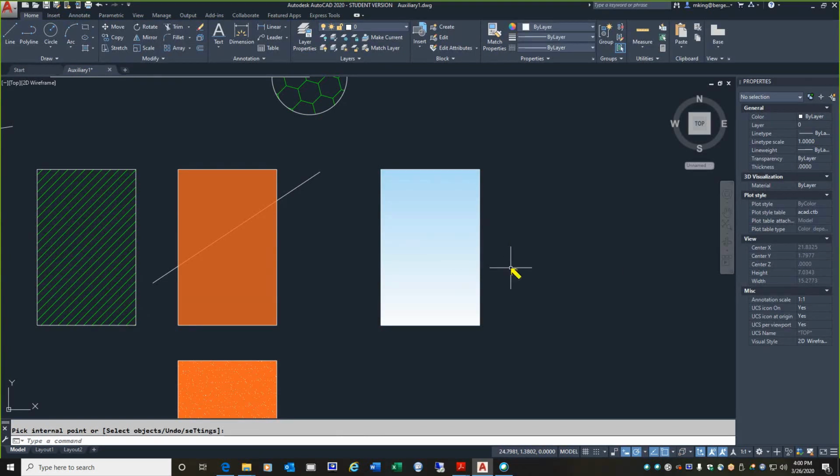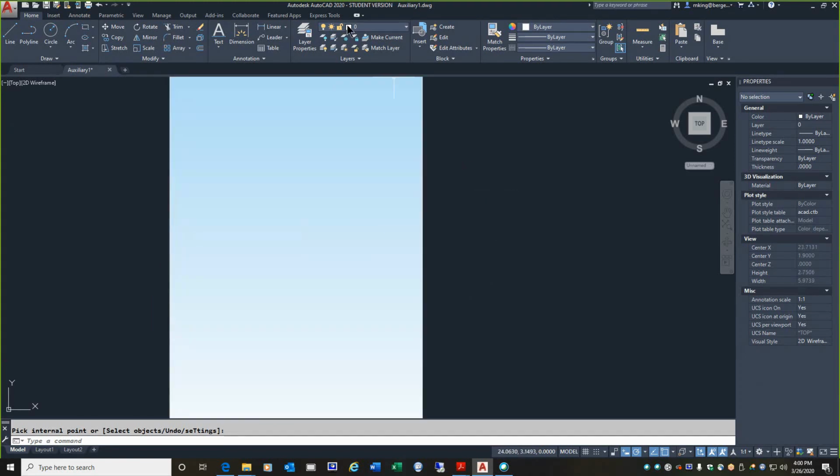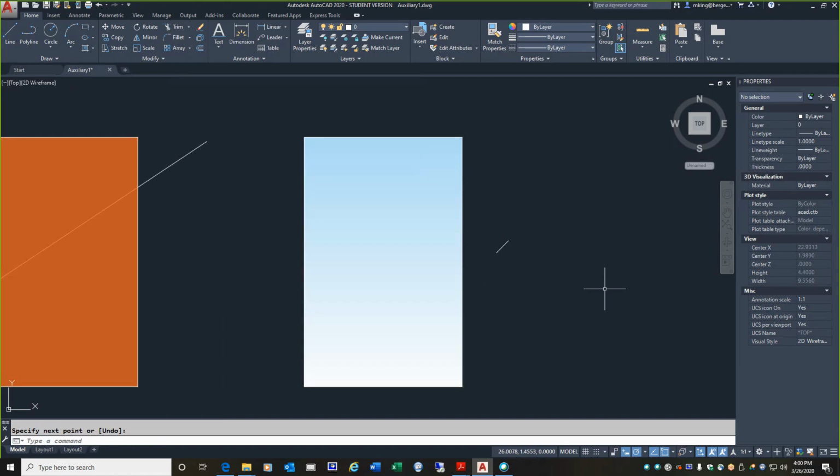And typically in windows for architectural renderings, you have these glass marks, just three little parallel lines that look like that. Okay, we're going to make them off to the side here. So I'm going to zoom in, and make sure you're in layer 0, go to line, and I'm just going to draw a line, let's say, on a 45-degree angle, not very big, good enough. Once you've drawn that little line, you can see it in the context of the full window.